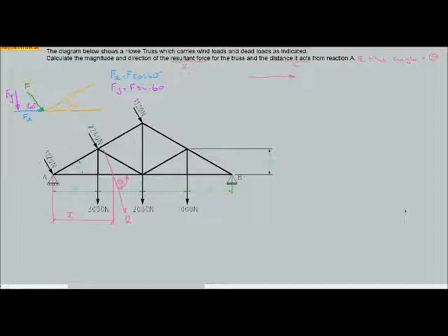So if we said the sum of the horizontal forces was Rx, and the sum of the vertical forces was Ry, the resultant is R. And if I take a little bit of trigonometry and Pythagoras, I can say that R is the root of, well, hypotenuse and the sum of two sides, Rx squared plus Ry squared, and theta will be Ry over Rx.